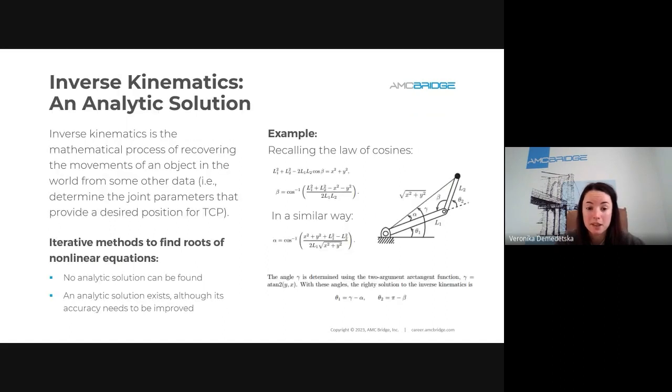And as you understand, the more popular choice is inverse kinematics, which solves the opposite problem. We have the position of the end effector, and from that, we want to understand how the joints should move to get into this position. So what are the theta angles for the joints that we need to set for each link in the chain?